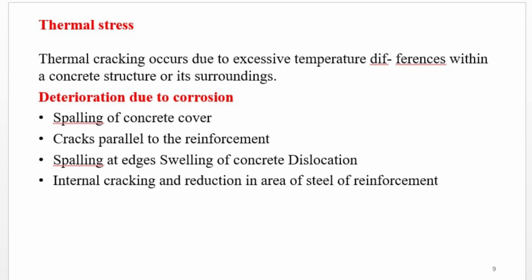Thermal stress cracks. The thermal stress cracks are cracks in glass or concrete that occur when there is a rapid change in temperature. Thermal cracking in concrete can be prevented by monitoring the temperature of the concrete mix, the ambient temperature and differential temperatures. The other ways to prevent thermal cracking generally include using low heat cement, using aggregate substitutes like fly ash, limestone or slag, using a low water to cementitious material ratio, and protecting new concrete from cold weather with external heat.